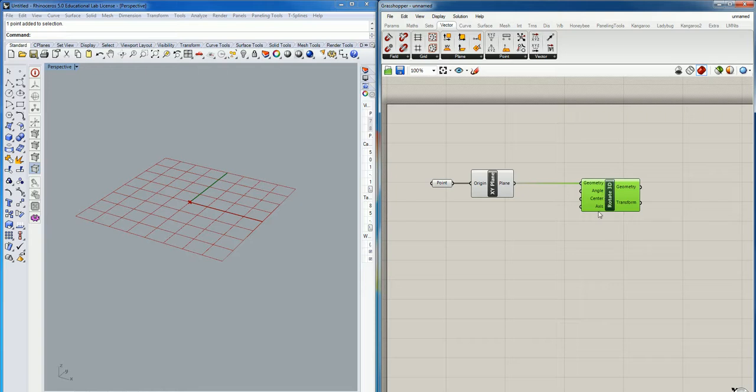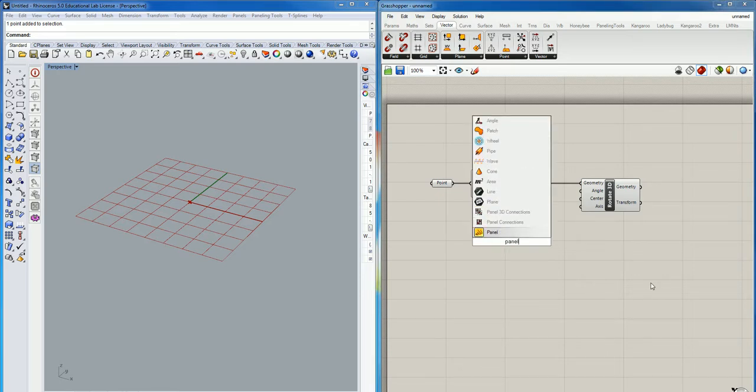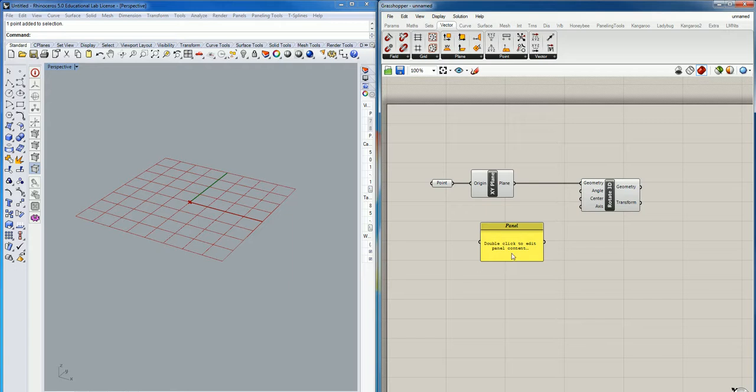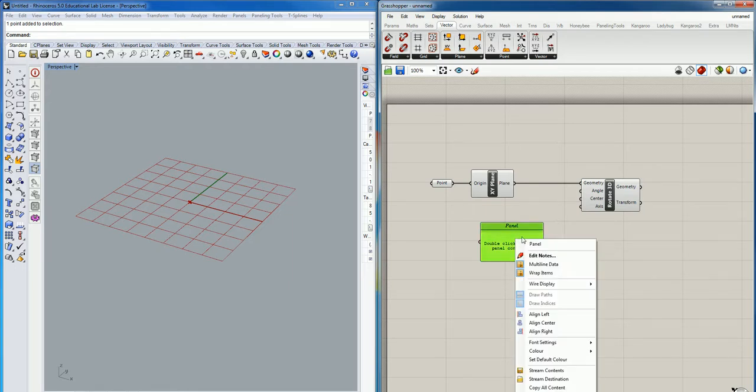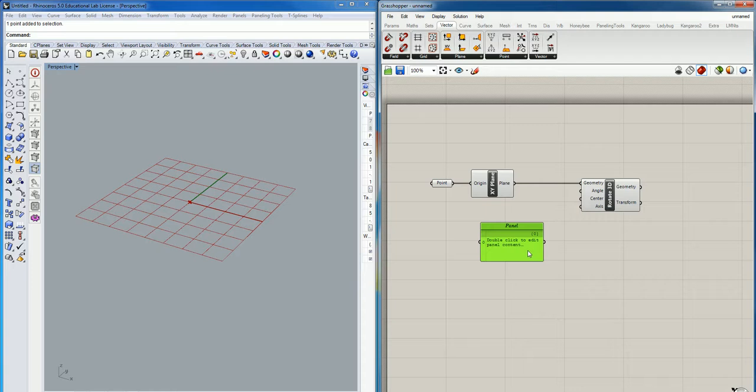So what I'm going to do is put in a panel here. And in that panel, I'm going to define it for multi-line text, even though I don't need to. I'm going to define one value. I want to define a vector that runs along the y-axis. So if I assume that I'm starting at 0 and I want to define a vector that defines the y-axis, what's my next set of coordinates? Starting at 0.